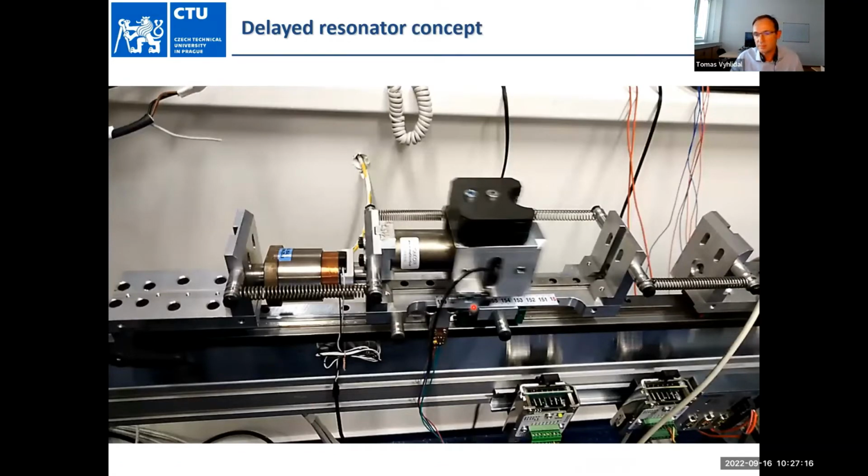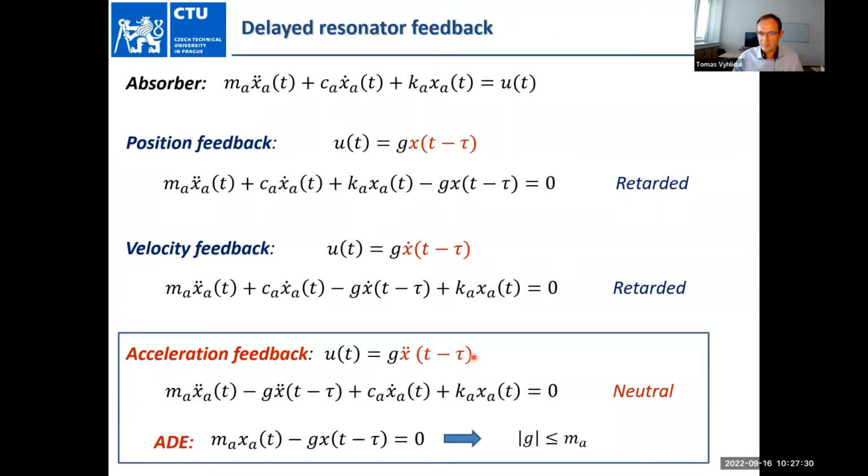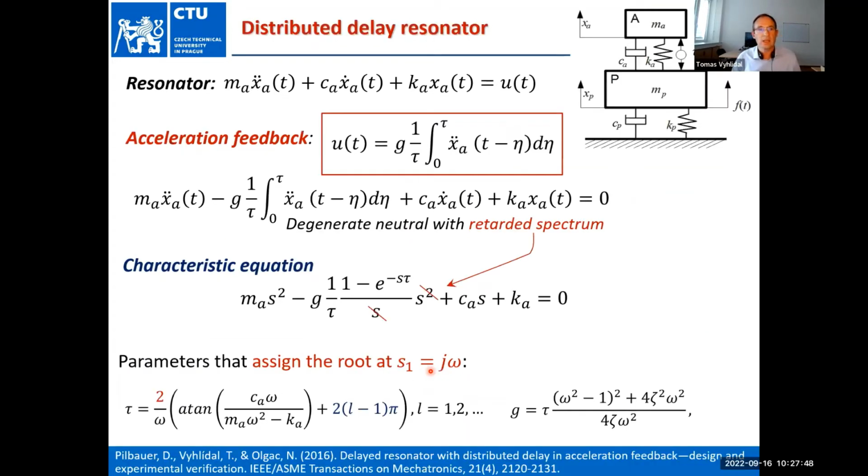In this experiment we used the acceleration sensor, but later on we moved to a position sensor, because of the disadvantage of accelerometers: they are usually very sensitive to measurement noise. That was partly the reason for the residual vibrations which we could see in the video.